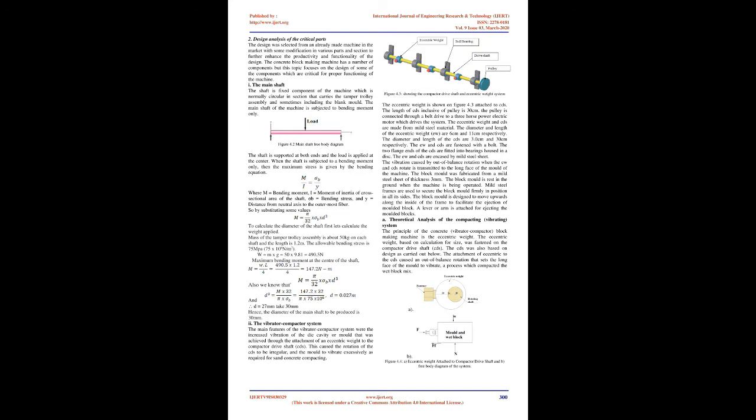The arm lever is part of the frame, and the design and shape of the arm is improved. Now it is simple for handling and manipulating. There is a stopper adjustment bolt for controlling the alignment between the mold and tamper during fitting or mating. Tamper release lever is in place for balanced and easy release of the tamper on both sides. Figure 4.1: The newly designed hollow concrete block making machine.